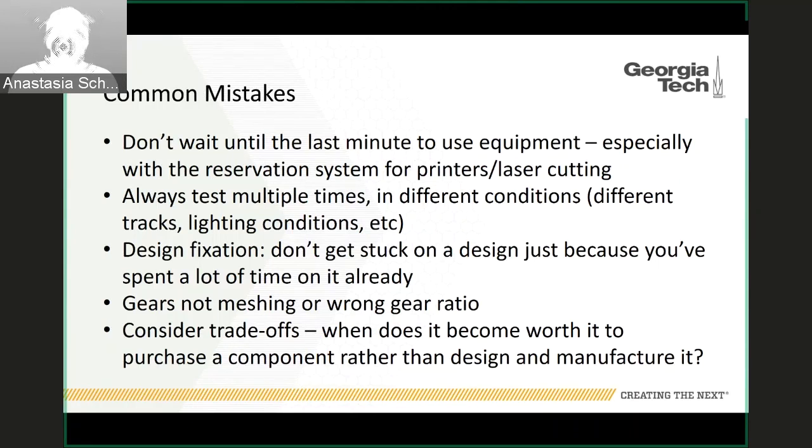If you are just really having a terrible time with gears, McMaster sells a bunch of gears made of plastic, $2 or $3 each, free shipping, one day. You'd know that they're going to mesh. There's not going to be a problem with that. So you should always think about when it is a good move to buy something and when it is a good idea to spend time designing and making it. Of course, you have to take your budget into consideration when you do this.